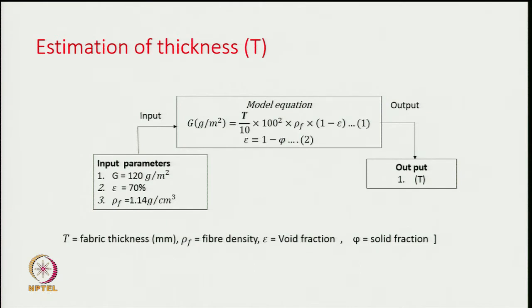Now, here when it comes to the estimation of thickness, the fabric basis weight is related to thickness, fiber density and porosity. That equation is stated here.